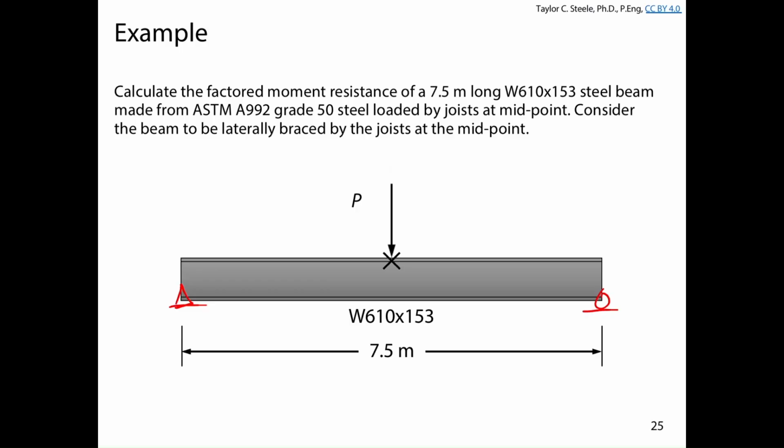Okay. So we already know that this is class 1, right? That doesn't change. So it's a class 1 beam, and we know that MP from the other day was equal to 1,587. Okay, so the first step would be get the section class and then calculate MP or MY. In our case here, we already know it's class 1 from last day, and that MP is 1,587.